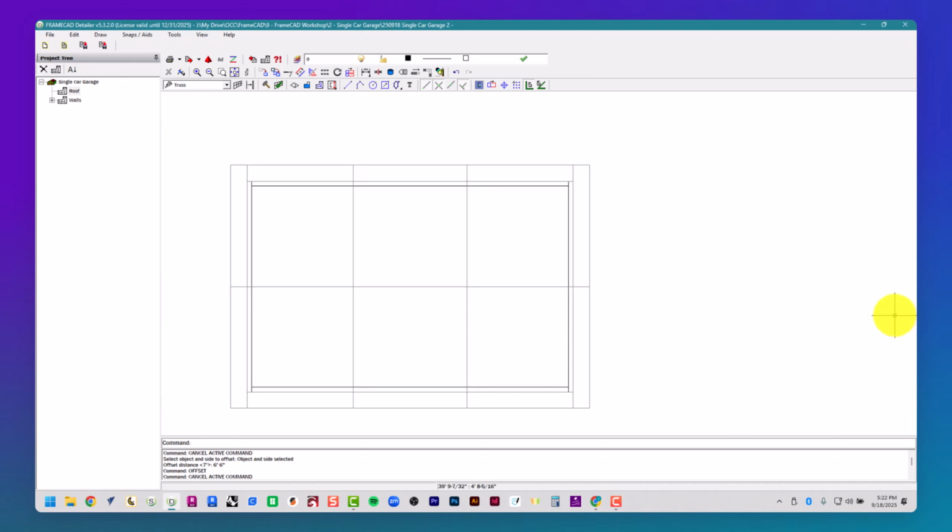Select Truss from the Frame Type drop-down box, and then place Frame. For my start coordinate, I will start on the far bottom of this line here, and I will end at the top of this line, and the side I want to grip the stick will be towards the right. Go ahead and click once.